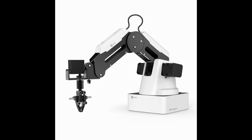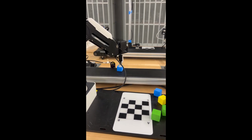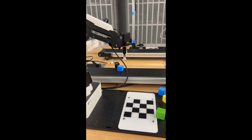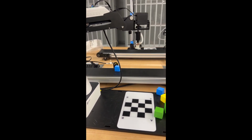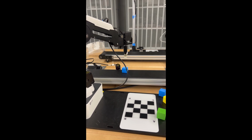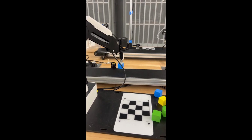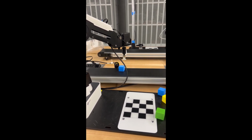For our first lab, we learned how to use the Dobot and its software, Dobot Vision Studio, and how to use point-to-point movement. We also learned how to use the IR sensor, and using these 2 different functions, we were able to place a block onto a conveyor belt, which we also programmed to run. When the IR sensor detected the block, the Dobot would use its suction cup, which was programmed to suction the block and remove it from the IR sensor.